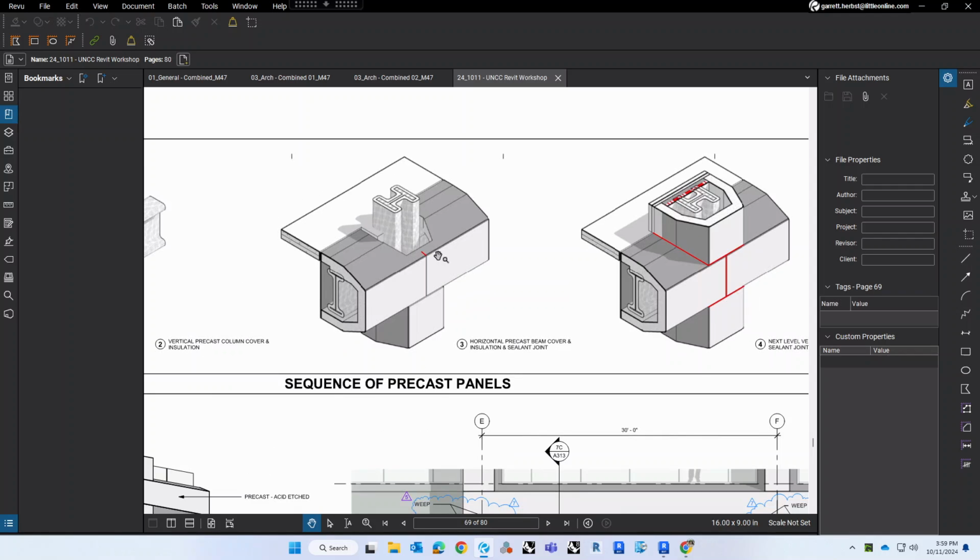So visually showing them, hey, you need to be sealing this as you're going, and then finally starting to put in the topmost precast, not only with the sealant but also with a ton of the fire rating and a couple other things, and then finally finishing with the curtain wall, and those relate back to specific, very detailed details.